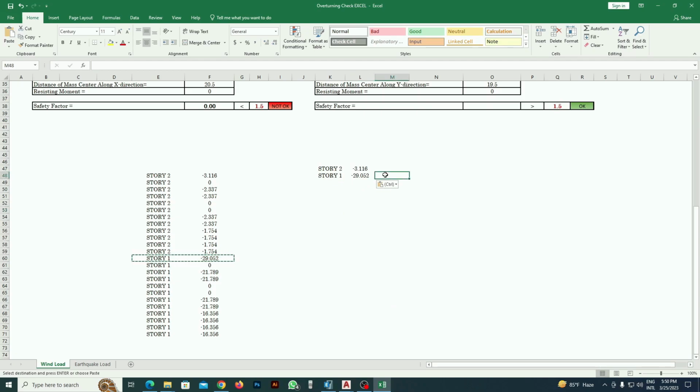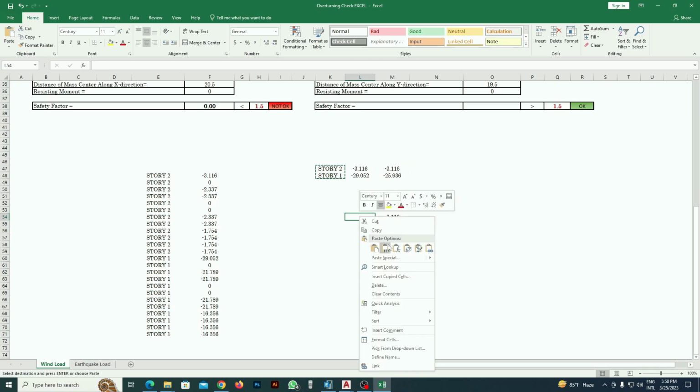Now what we have to do, we have to deduct story 1 from story 2. So press here, select this one minus this one, okay. Now here the remaining value will be the same, that means Control V, okay, fine. Now we can copy them, Control C, Control V as number, then you can copy them also, paste.